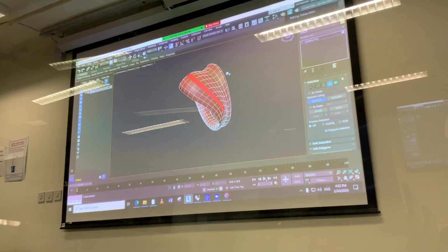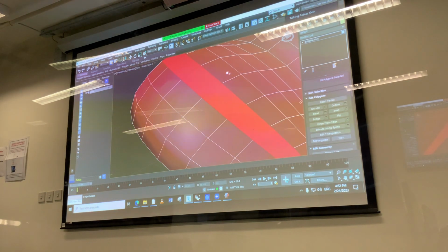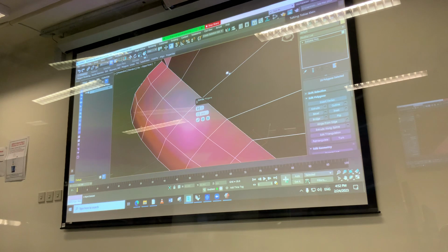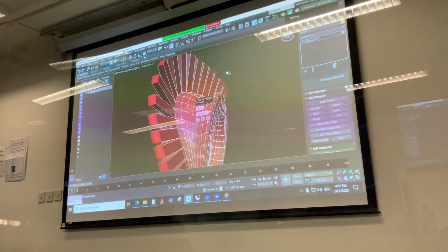Let's say, for instance, we want to use a little bit fun with these guys. So edit polygons. In polygon editing, we have basically 3 ways to interact. One is to push out, one is to pull in, and one is to connect. That's it. So I'm going to demonstrate. If I'm pushing out, I can use an extrude command and use that one either as a group or by polygons. Extrude commands are smarter because if you use bevel commands you use percentage, while in extrude you use numerical values. So that's quite useful.